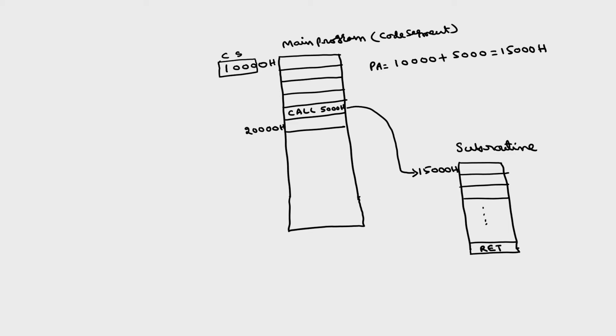For that, what this call instruction will do is, inherent to this call instruction there is a push instruction. The data that is to be stored here will be stored as the offset from here. So, what is the offset from here? If I write that this is 1000 and this is 2000, if I take only this physical address, the offset will be 1000.